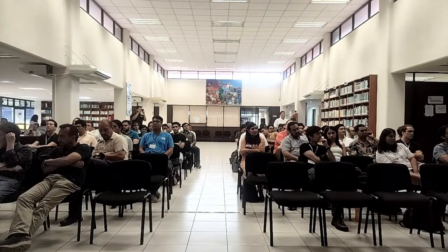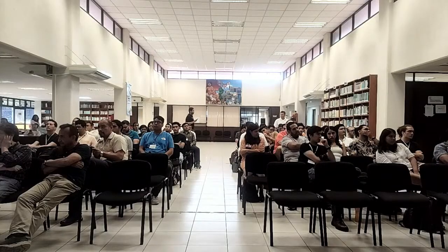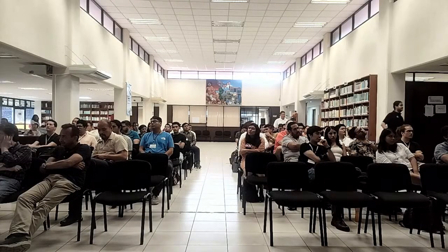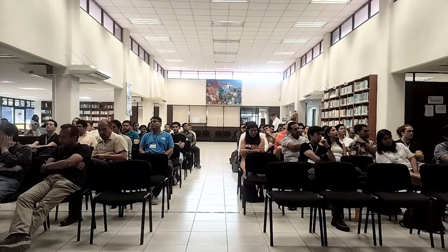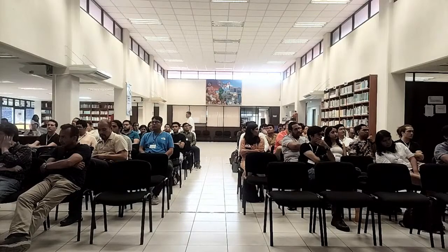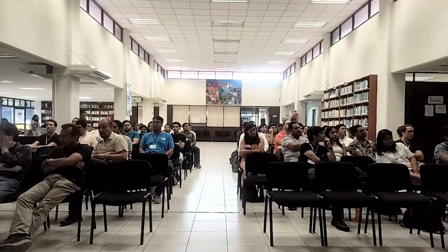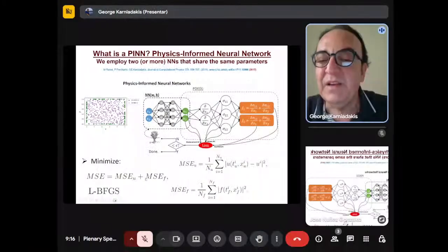We can take a linear combination of the first term on the left, the data, and the second term on the right. So now we take the data, whatever experiments you have. If you have no experimental data, this term is 0. Then we have to rely on the second term, just like we do in CFD today. But notice that we can have a few data points, and then we can combine them by using a linear combination of the physics and the data.